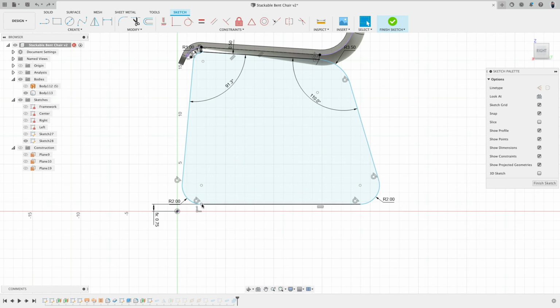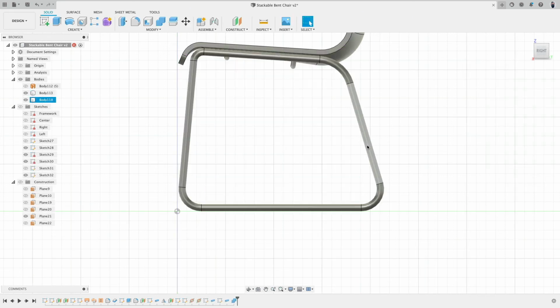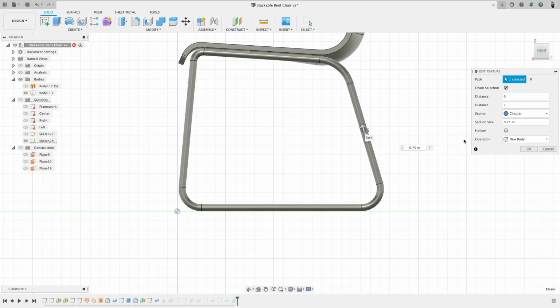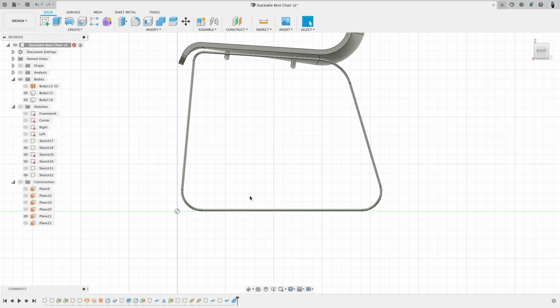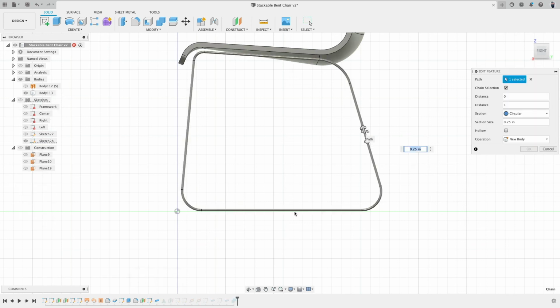This point basically only goes up or down. So we can select these 2 points, press D, and then here we specify a horizontal distance that now should prevent this from jumping as much. Yeah, there it is. Very good. Okay, cool. So the trick now is if we change the size of the pipe and say 0.25. You see that, how it goes down? Beautiful, no?